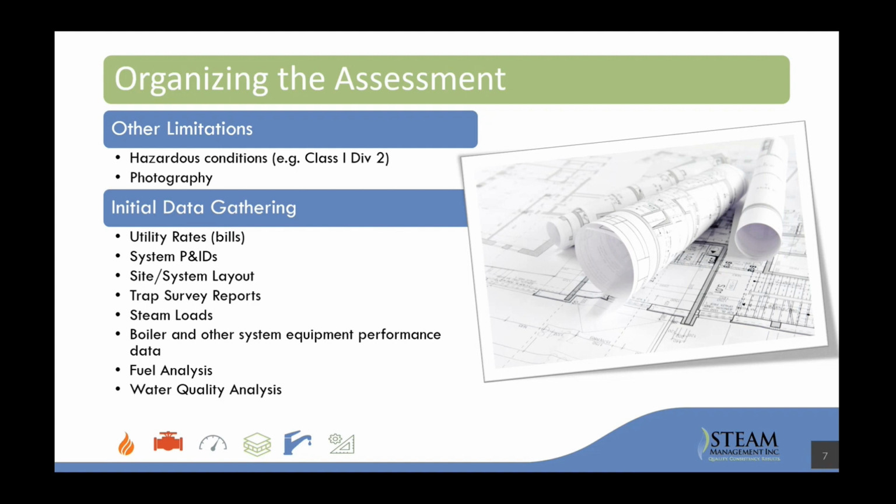Another big thing for steam systems is trap survey reports. So one of the biggest opportunities in steam systems is trap maintenance. And so at some point, most systems have had some sort of trap survey done, and it's great to get that report ahead of time so we know what the trap population looks like and what we're getting into there, particularly if we're coming on to do a detailed trap survey.